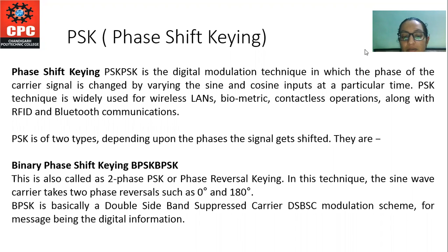The input binary information is encoded into groups of bits before modulating the carrier, so that in phase shift keying, the phase of the carrier is varied to represent 1 and 0. Both peak amplitude and frequency remain constant as the phase changes.